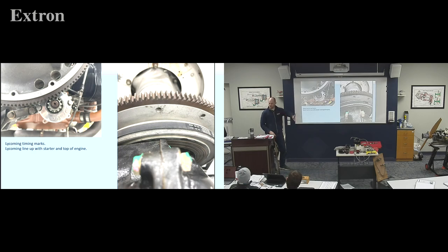It's right up closest to it. So a Lycoming engine has the number 1 cylinder right up by the prop, because it's the top dog engine. So if you remember those 3 things, you'll always know where to line up that TC on a Lycoming: top of the case, valves are on top, and number 1 cylinder is closest to the prop.